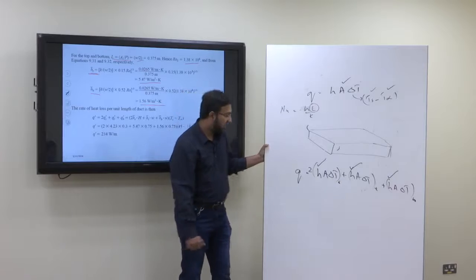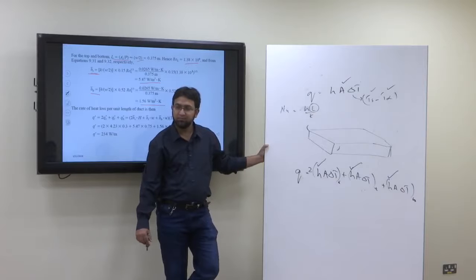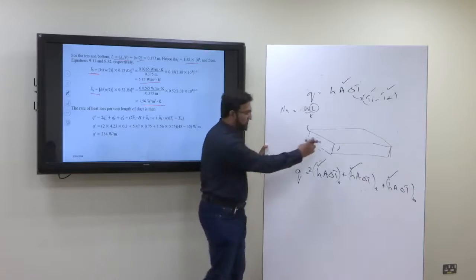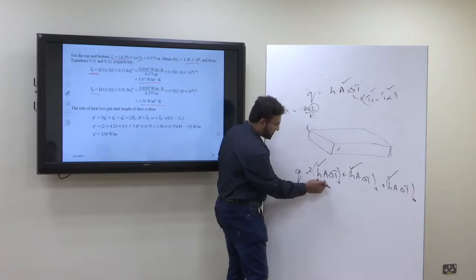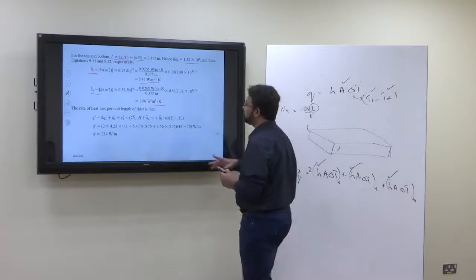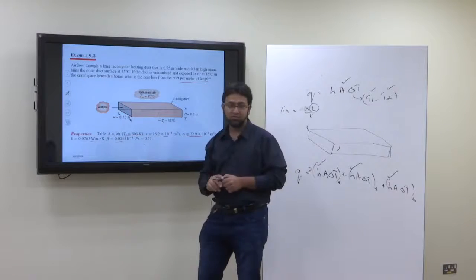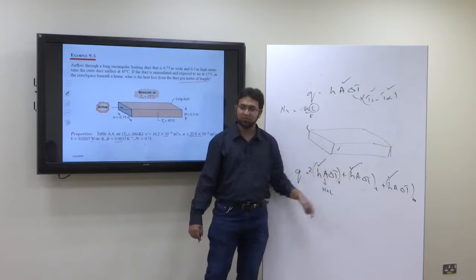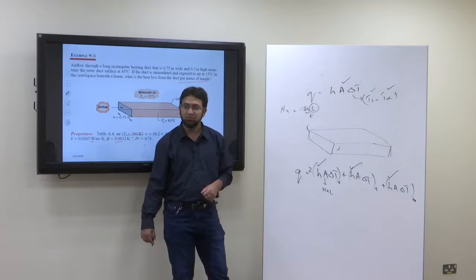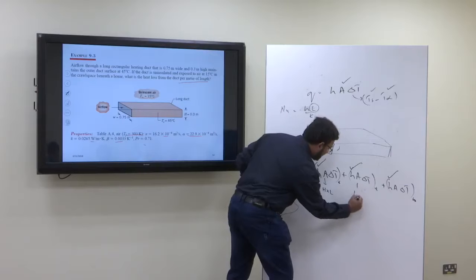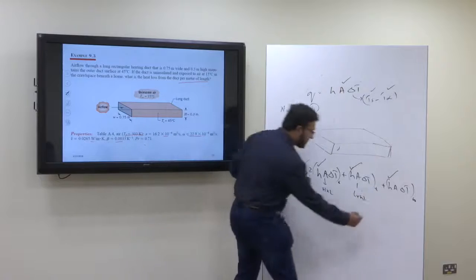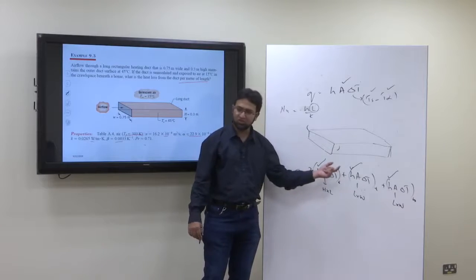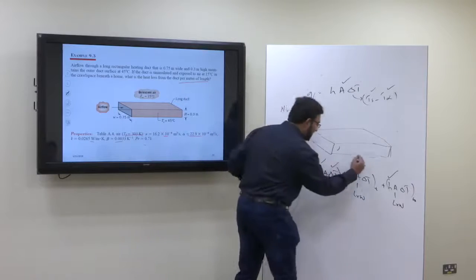Right? Okay, the surface area for the side, what will it be? If you want the heat loss per unit length, not area, the side is H, so the area will be H by L for the sides. For the top, the area would be W by L, and for the bottom, L by W. Okay, ΔT: will it change for the three cases? It's the same, Ts minus T infinity, right? So we know ΔT for all three.